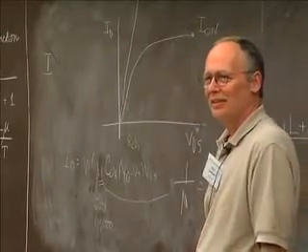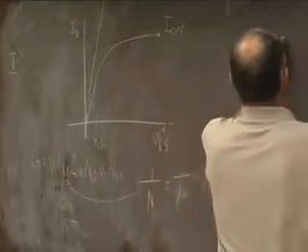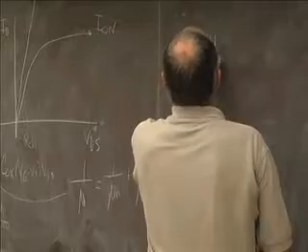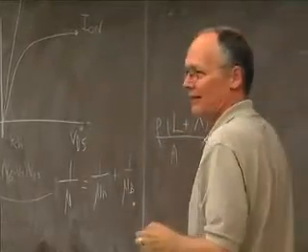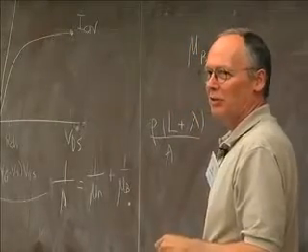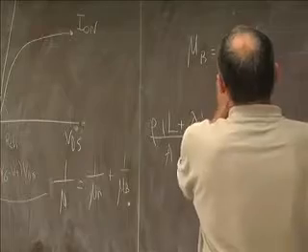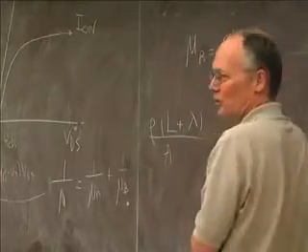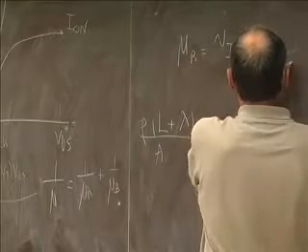And that's the thing that depends on channel length. So that ballistic mobility is thermal velocity times mean free path, but in the ballistic limit, the mean free path is the channel length, divided by 2, that's the diffusion coefficient, and then the Einstein relation divided by kT over q.